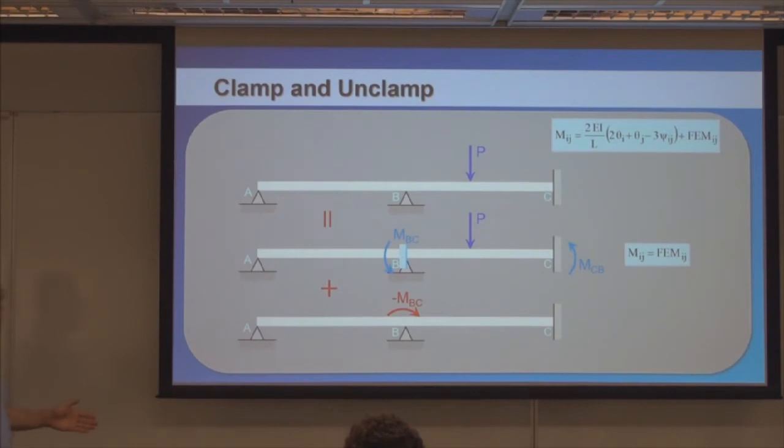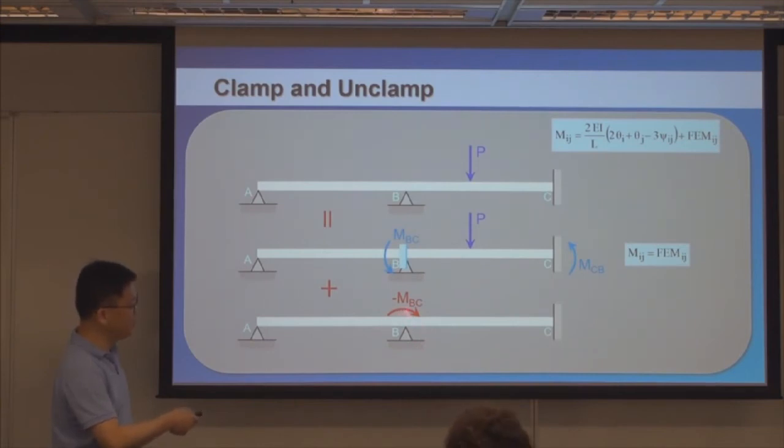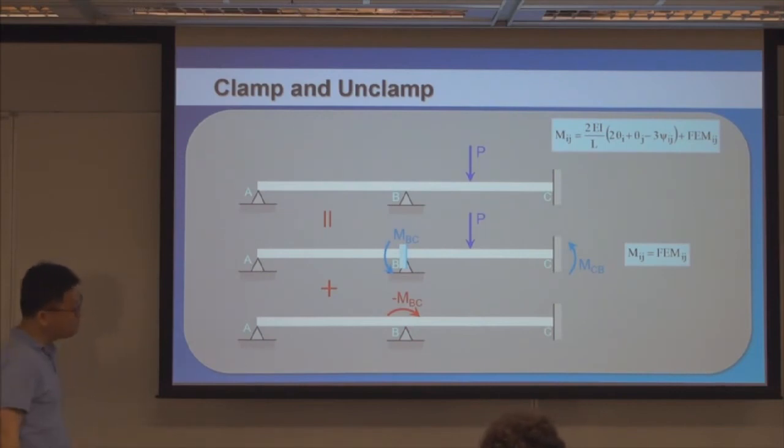By doing so, you can achieve the purpose of converting the loadings acting on the components to the loading at the joints, which is quite clever. So basically, following the superposition concept: clamp it first, calculate the end moments, and then apply backward, trying to cancel that. And then from this point onward, it's the same as the previous example. You can directly distribute the moments into the component and then carry it over to the other end. So this case plus this case equals the original case.